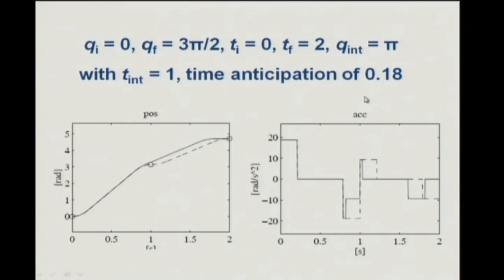And what this does in this process is, you start with the trapezoid, so this is a parabolic profile, it goes here, now instead of coming down here and getting 0 velocity, it just kind of passes over this and goes kind of parallel to this path, and then finally you reach the position here a little ahead of time because you did not slow down here, and you attain that velocity using this method.